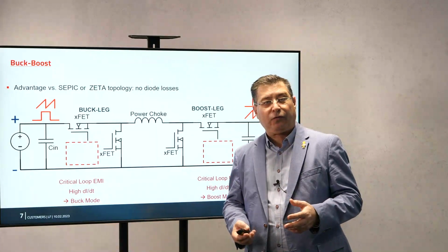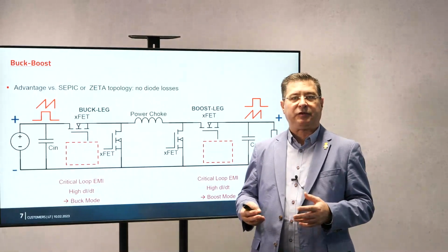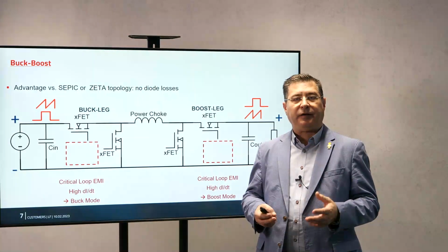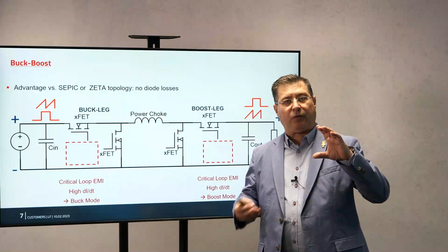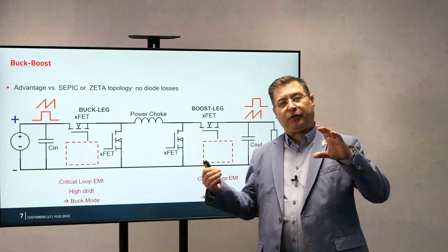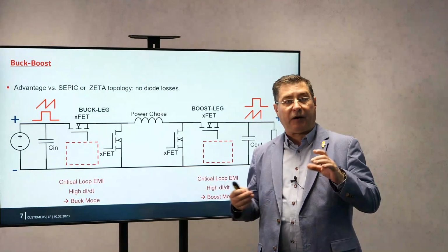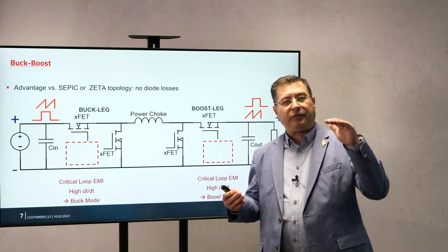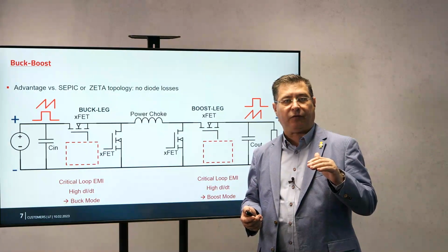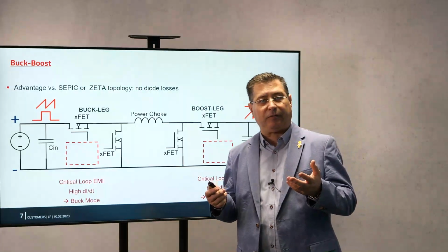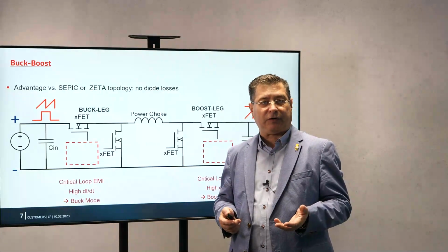If you look at power supplies today, almost everything is somehow battery operated. And the battery, when completely charged, has 3.6 volts. You need a 3.3 volt output, so you have a buck conversion. And when the battery starts to get empty and falls below 3.3 volts, you need to boost the voltage. So very often you will use a buck-boost converter.